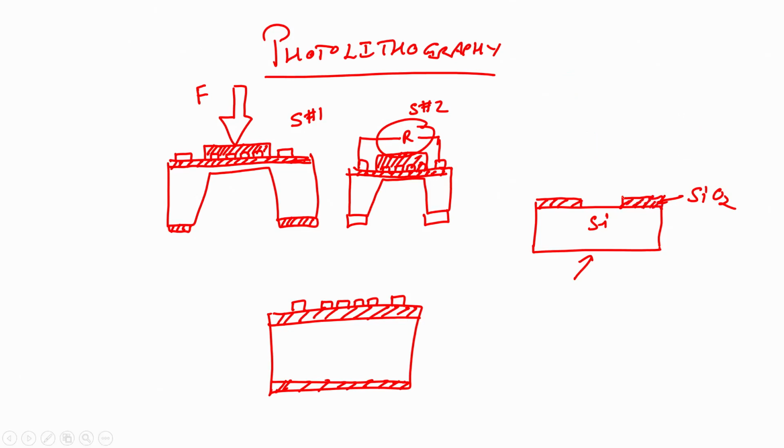SiO2 will not be affected, right, and the photoresist will be stripped off, correct. Now, the next step is I will go for DRIE, deep reactive ion etching. What will happen? It will etch silicon, and it will give me a step, correct. This is what I want, why?